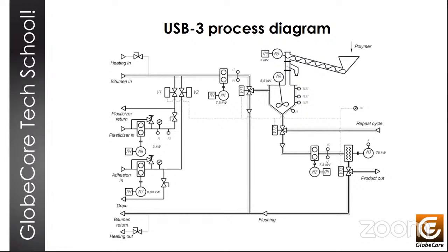In this tank during the operation, the bitumen level is constantly monitored and maintained between the level sensors. There are a high level sensor and a low level sensor, HLS1 and LLS1 respectively. It's done by controlling the M2 pump using a frequency converter, and this frequency converter operates depending on the signals received from these two sensors. The M2 pump pumps out the polymer bitumen mixture from the M4 mixer. The polymer that is evenly distributed in the bitumen is ground and homogenized by the mill, M3.